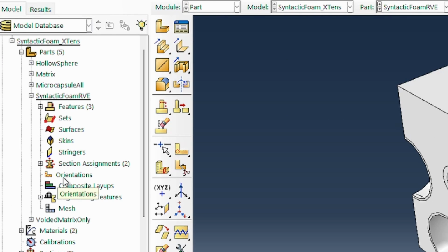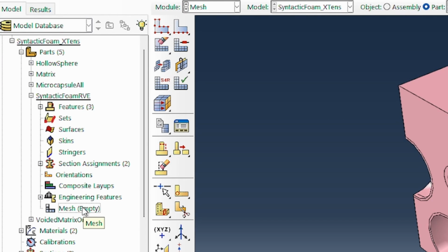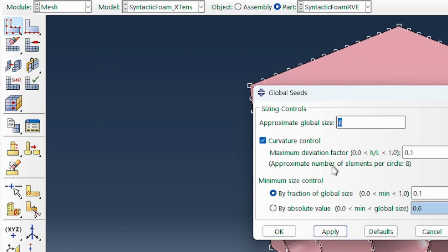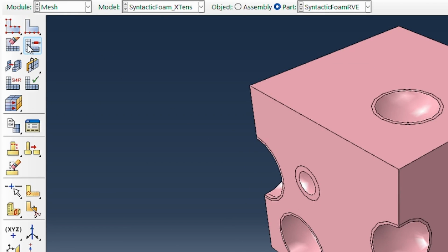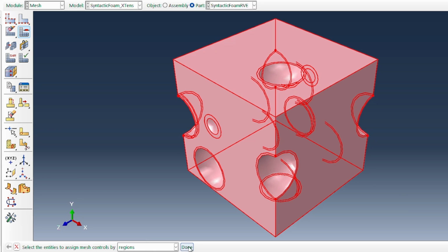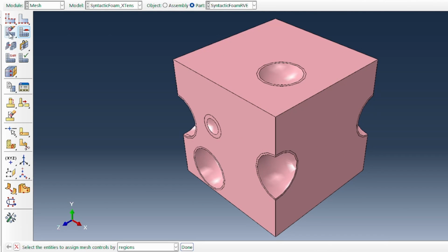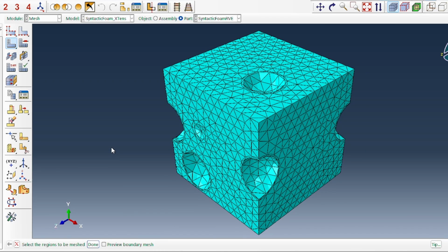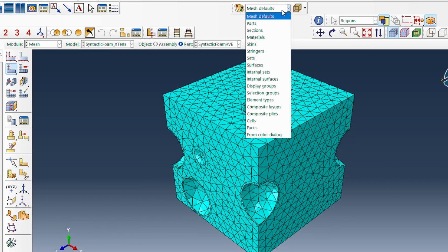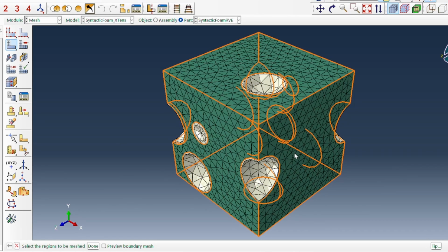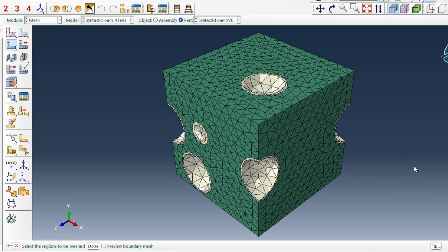There are a few things that we're going to do. The first thing is to explore meshing this model. If you double click there, it's giving me a mesh of about 6. I'm okay with that. Then I'll select all of that and associate it with a tetrahedron. Tetrahedron normally will work well for this structure. So we need the meshing tool, which is the very first one here. If you select that, that gives us a mesh model that we're working with. If I switch this to the material model, it looks okay, and we have a good structure that we're going to work with.